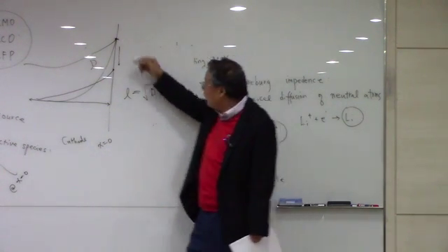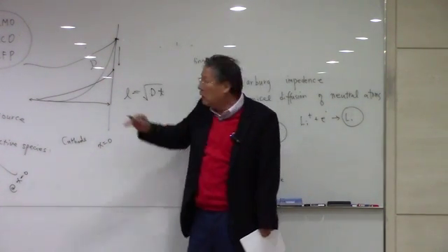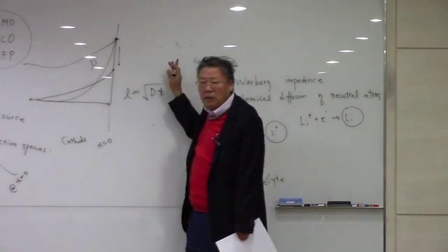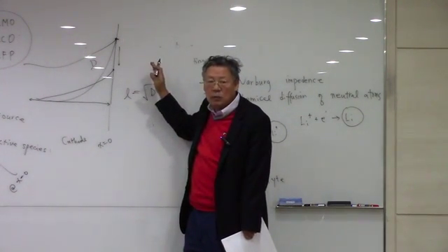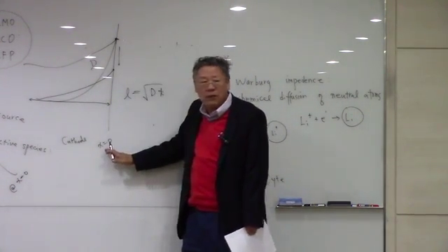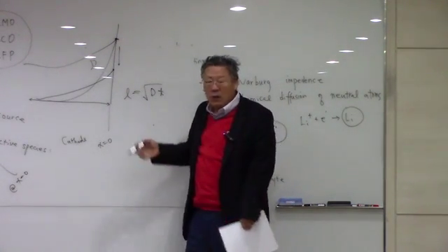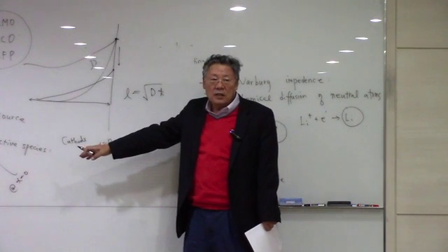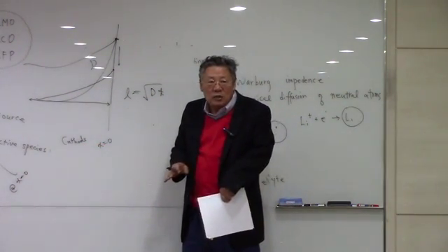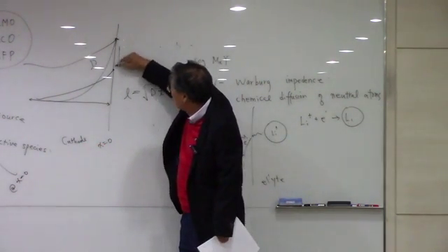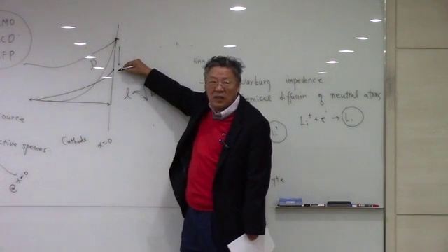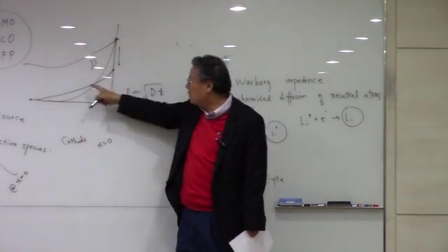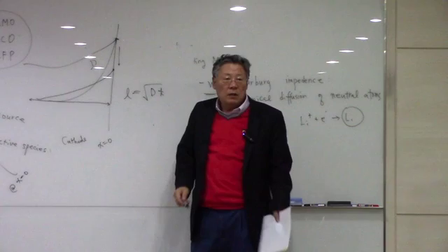So if you have a high diffusion coefficient material, then at the same amount of lithium or electroactive species piled up at the surface electrically, the voltage that you are going to obtain is not going to decrease much, because the surface concentration goes down instantly because of the high diffusion coefficient.